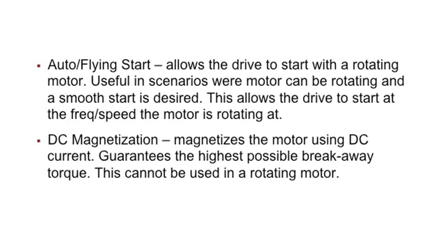There's a couple different start modes available to us. We have a normal start mode that'll happen if you just plug in the drive and auto-tune it and start going. But sometimes there's a need to catch a motor that's already rotating. For example, on a fan application, that motor can what we call windmill: the airstream can literally make the motor turn when the drive's not even running.